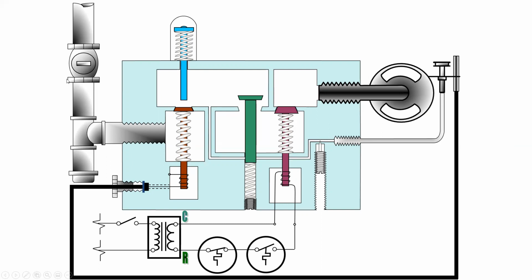When we look at the flow of gas, the gas is going to have to first enter this chamber, and then when this valve is opened, it will seep into this main chamber here where we see a green regulator. The green regulator is simply something that regulates how much volume of gas is flowing through to the burner and not something that electricians typically are involved with. Over here is the main gas valve. It's much larger, and this one is energized and drawn down when the thermostat, which is located here, calls for heat in the room.